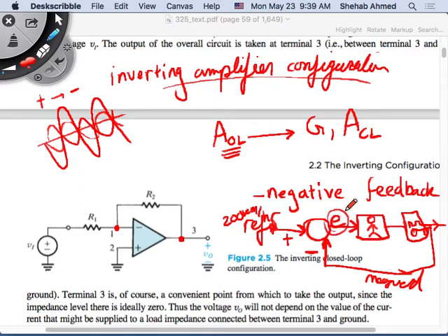This error signal, this input signal that was based on measuring these two, and this is called negative feedback. I am giving negative feedback to my controller. This is the controller. The output from the negative feedback is going to my controller, the human in this case, or the computer, right? So positive feedback will do something completely wrong. I'd be measuring something, I'm going to be adding it to the reference. So I will always be having this huge margin. Do they use it? No, positive feedback is not used.